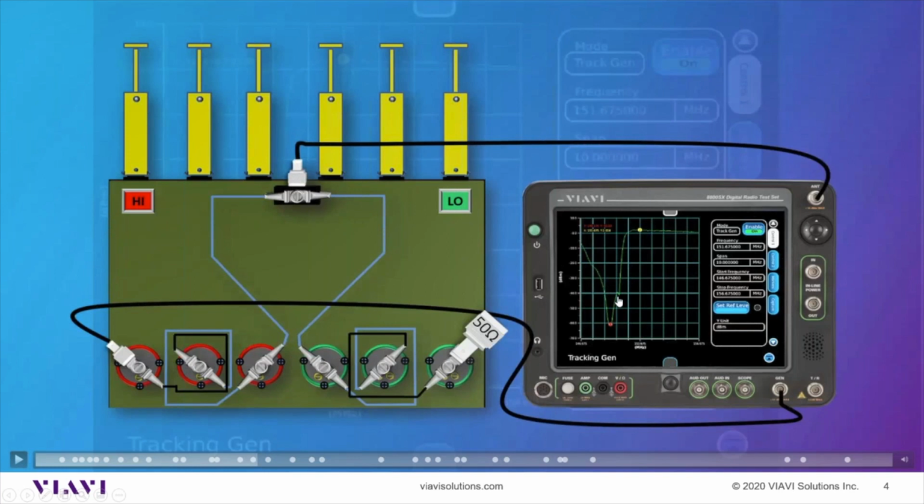So you can see that we've got a few anomalies, a few lobes hanging out, and so we're just going to go back through. All three of these cavities are interactive, by the way. So you're just going to make movements in these plungers to try and straighten these out and get these lobes out of the way. What that does is it will peak out the pass band, and it takes a little bit of time, and you might even have to make a couple of passes at it to do that.